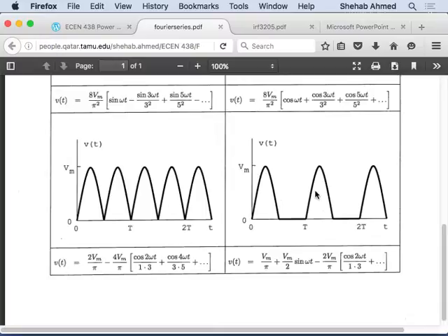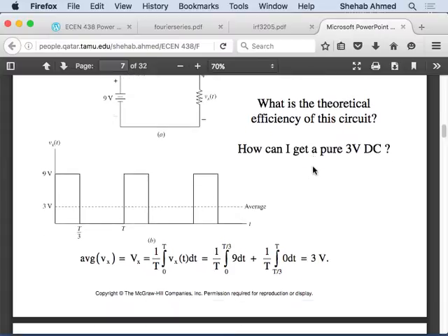If I put a low pass filter anywhere above DC, fine, I'm happy, because I'm switching typically in the hundreds of kilohertz or tens of kilohertz, etc., and then I have something at 0. Right? So I put a low pass filter. It's easy. I will easily take out the average value from the original waveform. So that's exactly what we did. We put a low pass filter.